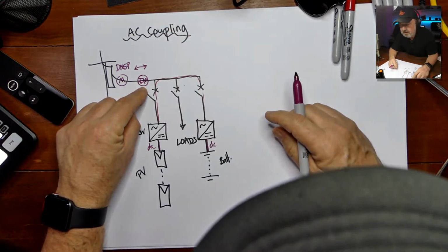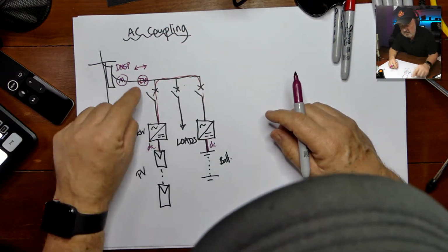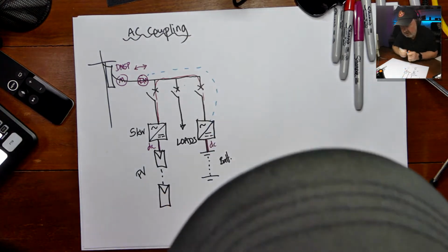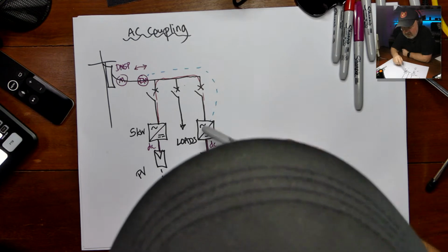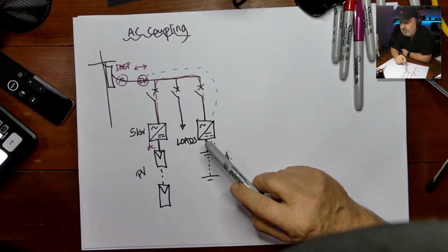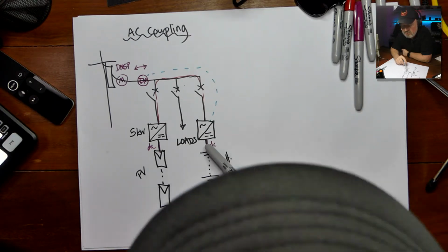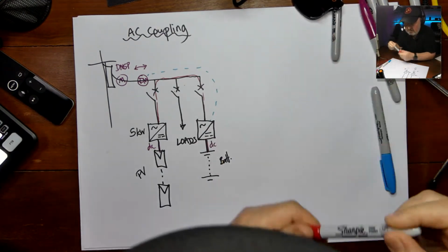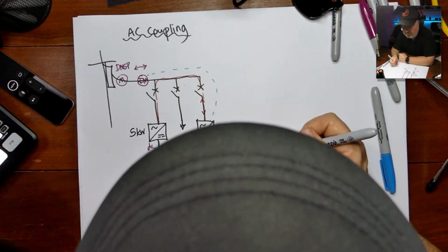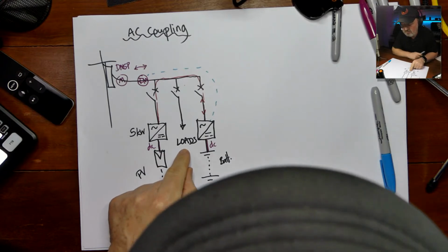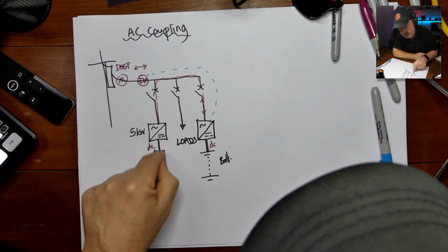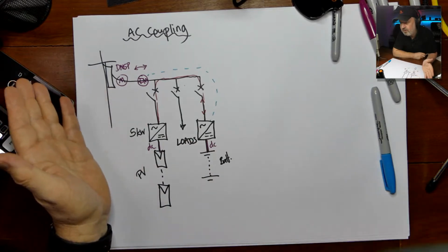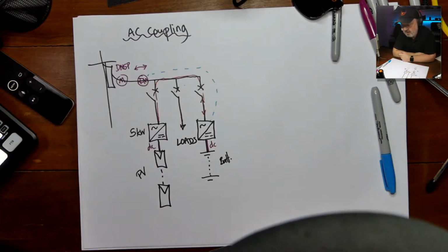So it's actually a measurement device to look for opportunity. And the opportunity is being communicated through to your battery inverter. So there's a comms link, communication cable, that goes through to your battery inverter, and it tells the battery inverter, is there an opportunity to charge from free renewables? Or is there an opportunity to displace expensive grid power with stored energy? So a battery inverter is a bidirectional device. So this system can import or export power, and so it can choose whether to support the loads or to import energy when the solar is generating and charge its battery. And of course it can do that in any combination. So it can be partially exporting to the grid, partially charging batteries, etc. That's AC coupling in a nutshell.